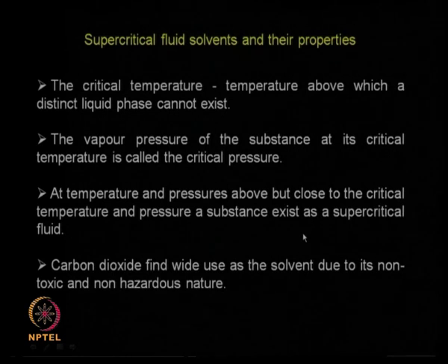Why carbon dioxide is used? As I said, it has got a reasonably good supercritical temperature and pressure, number 1 and 2, it is non-toxic and it is not flammable, it is also non-hazardous. So that is why carbon dioxide has become extremely popular. And another advantage is, as soon as you reduce the pressure, the supercritical carbon dioxide will immediately go into gas, leaving behind your metabolite or aroma or whatever solute you are trying to extract. So that is the main advantage. Then again you can pressurize the carbon dioxide and convert it into a supercritical fluid.